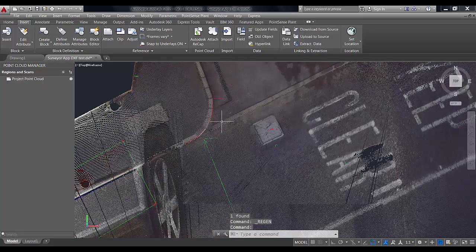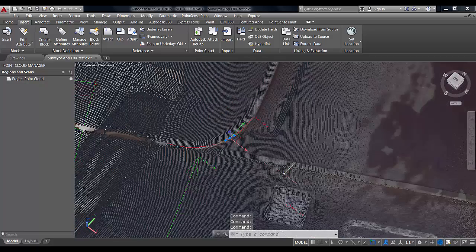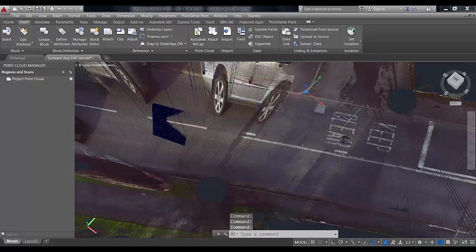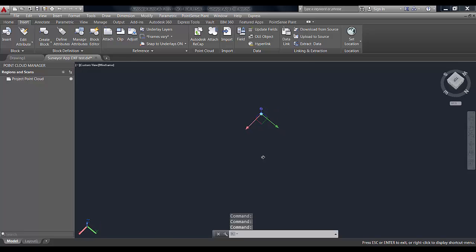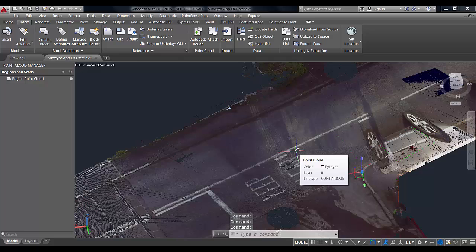So you can see the line work that we created in the Surveyor tool has come through in the correct place and lines up with the point cloud. In this instance now, we have a couple of options. What we could do is augment this with some additional information in AutoCAD, which we can then bring into Revit as a DWG file potentially, and give us an outline to divide up our topographic surface we created in Revit from the CSV file export, as shown in the previous webinar.